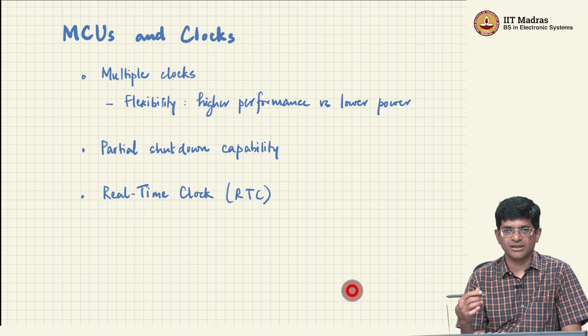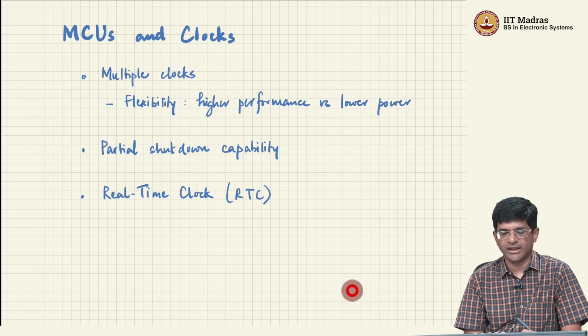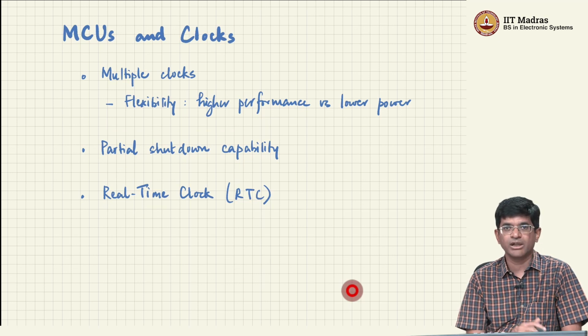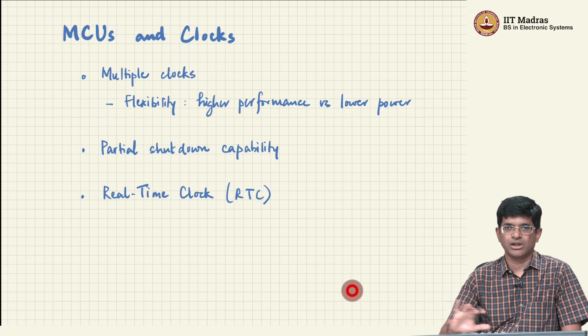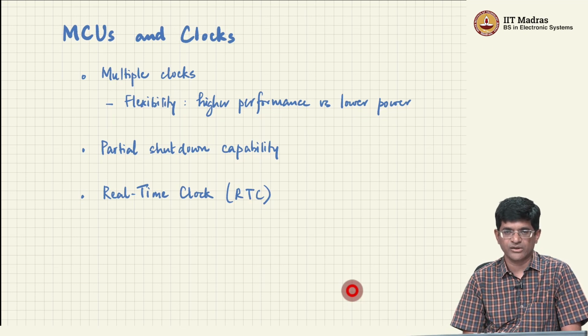So that's why this is considered a useful thing to have and is actually made use of while building complicated embedded systems. It allows you actually to partially shut down parts of the system. So you might have a microcontroller where perhaps for your particular application the entire communication subsystem, the I2C and SPI buses and so on, are not going to be used. The good thing is you can just shut off the clock, and in fact you can even shut off power to those parts of the system and thereby save on power, right? Remember that power only gets dissipated when there is actual transitions on the gates. So if I shut off the clock, make f equal to 0, presumably I should be able to save some amount of power.